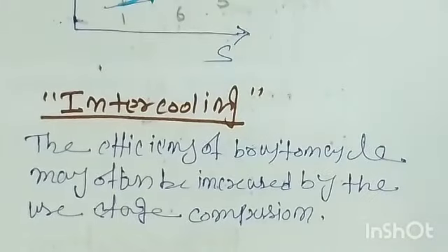In intercooling we use two compressors, the low pressure compressor and the high pressure compressor. The purpose is that we are trying to split the work input in a compressor, right? But always remember that when you use intercooling or reheating, it won't directly give you better thermal efficiency. If a gas turbine plant works only on intercooling, it won't increase the efficiency of the plant.